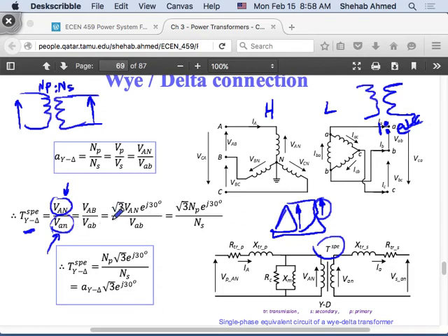So remember this, if we have some voltage on the primary side, what voltage do I have here on the phase? Which voltage is higher? So remember this line voltage is coming from my star on the primary side. So I have a transformer and a fictitious load, right? The transformer has a phase A voltage, right? And the fictitious load has a phase A voltage as well, right?